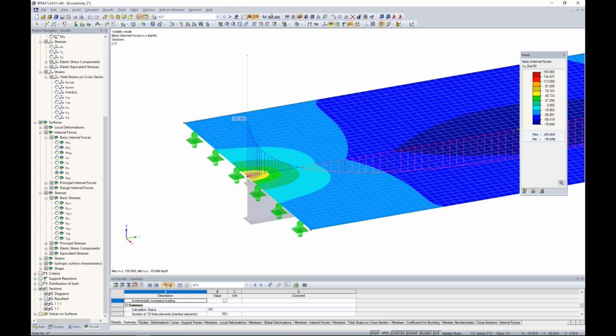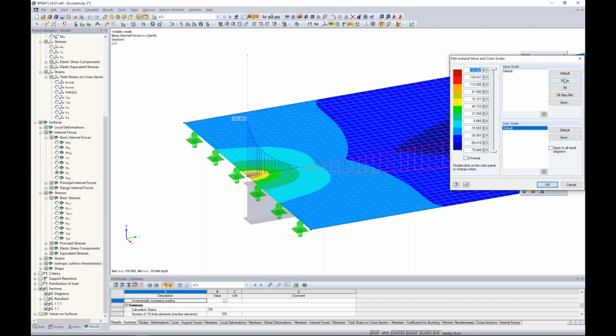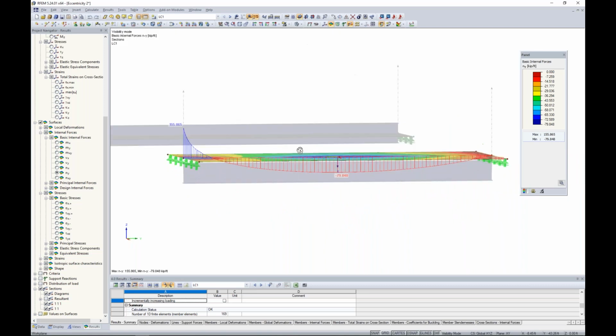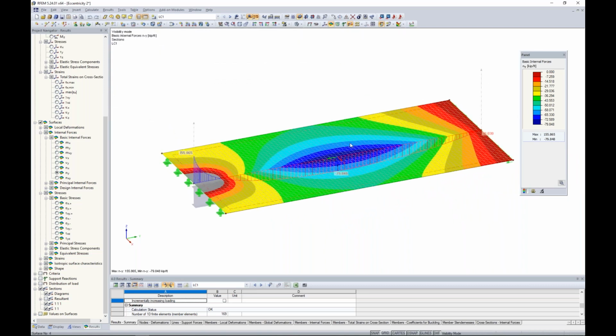So we could probably use an average region, maybe rigid links to kind of take care of that. In our control panel, maybe we completely take out tension and we adjust this control panel here only to look at the compression forces. And it's really as we'd expect. We want this slab element to take those compression forces from this applied area load.